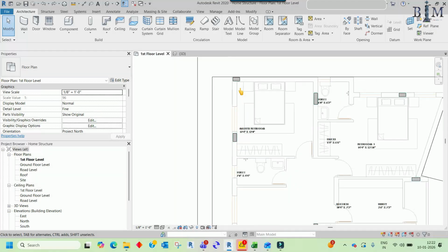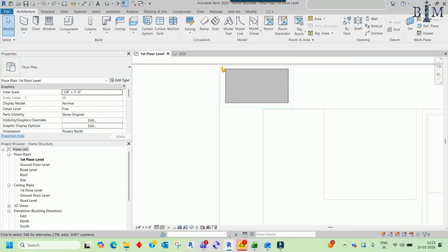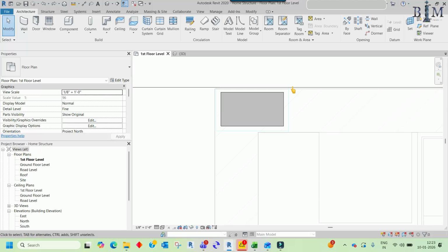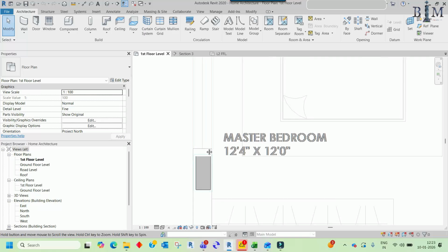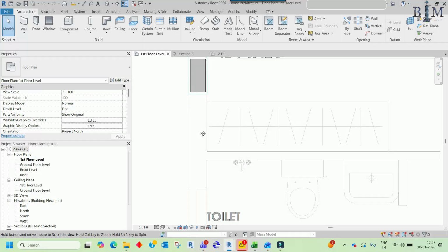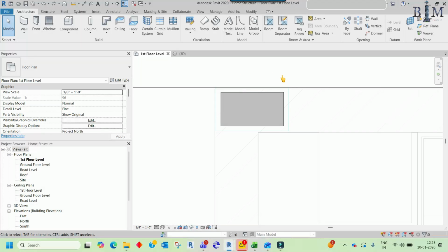And here, what we need: you can see the covering wall around the column that we need to draw. Where can we draw it? Because in the architecture, if I make it, then the beside wall can join automatically. So if I make this wall in the structure, it will be helpful and very good to model, and there will be no auto join. So let me start here. Go to the structure, and here I need to model the cover wall.